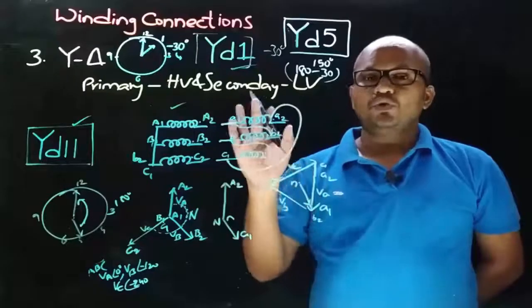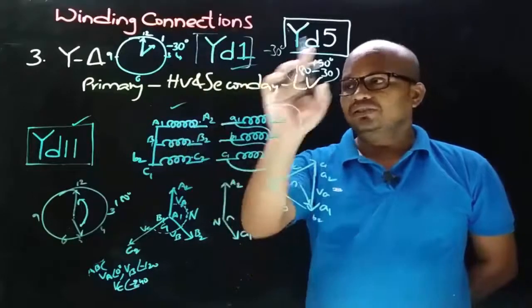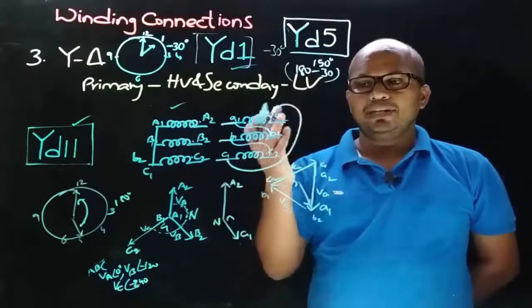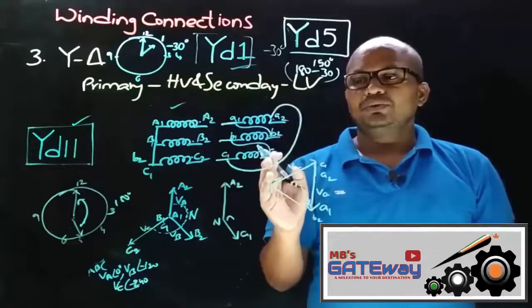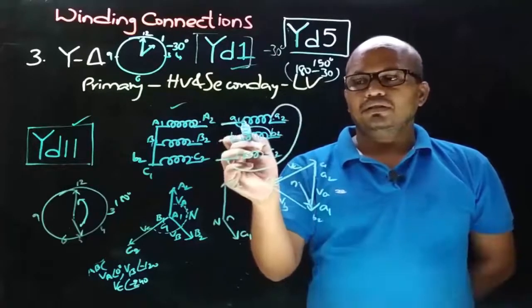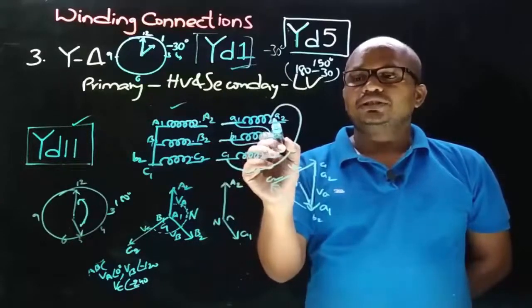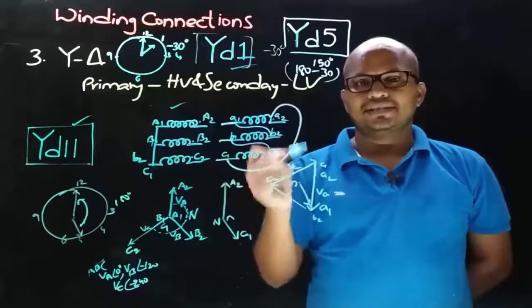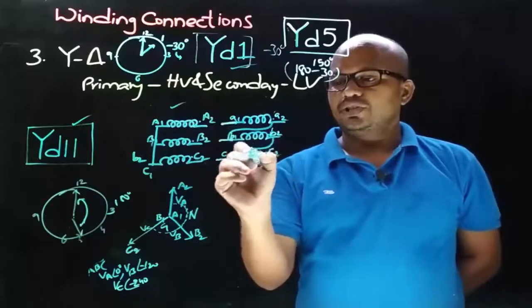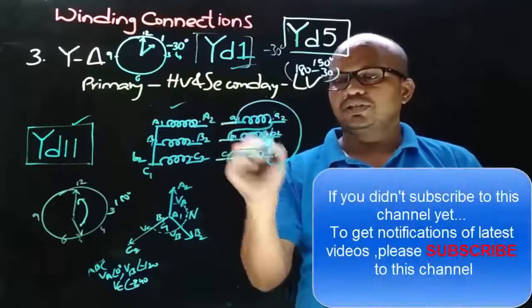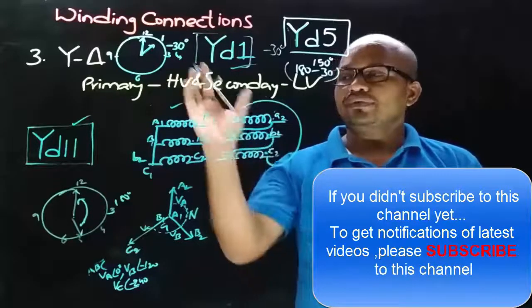Now let's discuss the fourth possible connection of the star delta connection. On the primary side, the connections are left unchanged for all the four possible connections, and the change here we are making is on the secondary side winding connections. And in the fourth case, what we are doing is taking the connections from non-dot ends and joining the dot end with non-dot end. Let's see that. So here we are joining the dot end with non-dot end, dot end with non-dot end, dot end with non-dot end, and taking the connections from non-dot ends. So this is the fourth possible connection of the star delta connection.